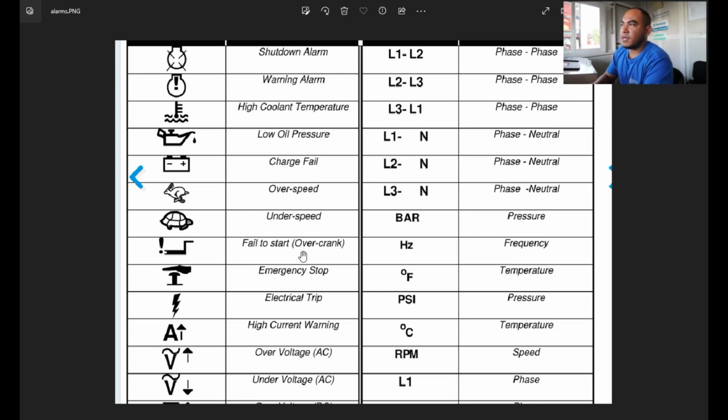So what are the causes of that? Again, fuel blockage, air in the fuel line, failure of your injector, or either water in the fuel. You have to check one by one what is necessary, so that troubleshooting is easiest for you to achieve and fix the problem.